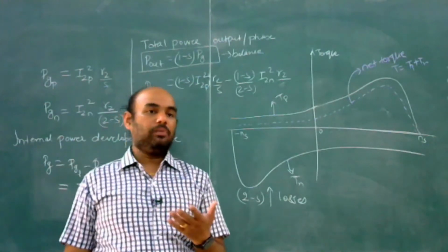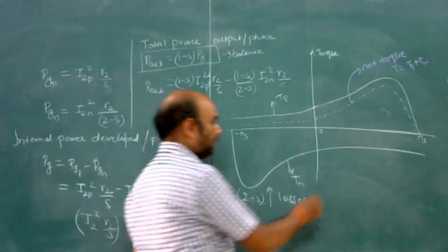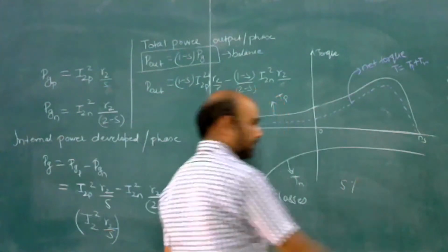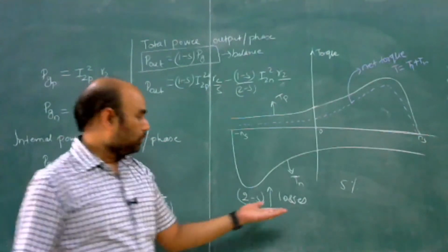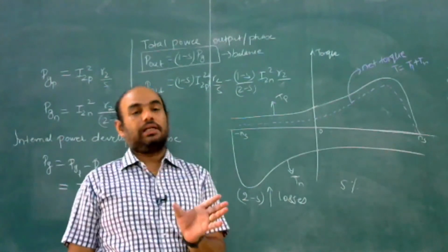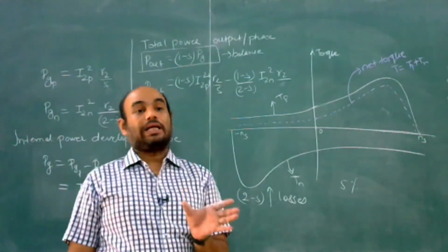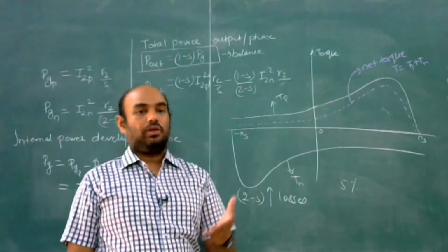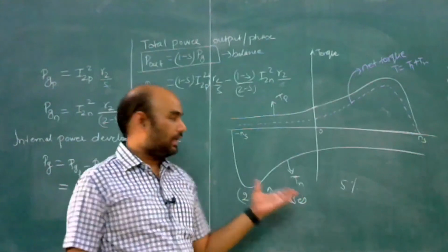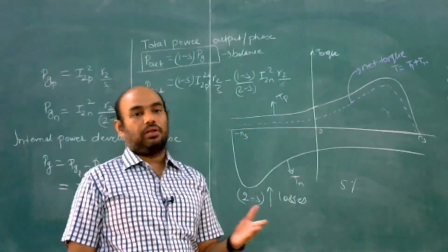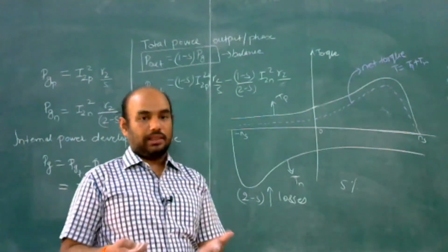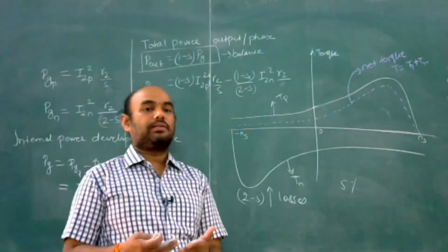So the permissible limit of this unbalanced voltage is 5%. Okay, so to avoid this overheating due to these losses, we generally connect a negative sequence relay, which detects this unbalanced condition, and it will trip the motor if there is heating beyond the preset value.